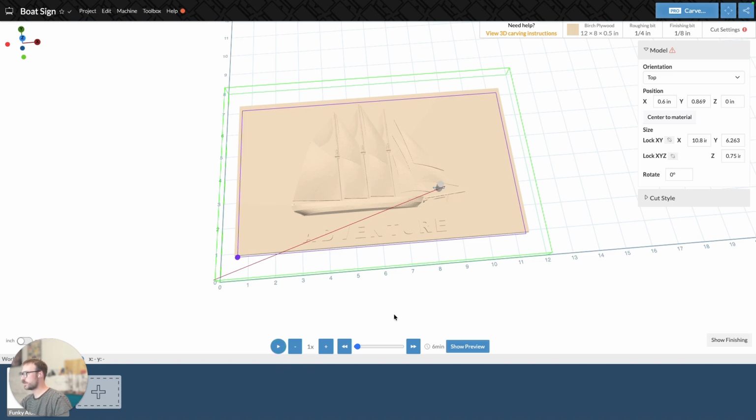That is basically where the position works out from. So if we look on the x-axis, it's about 0.6 of an inch, and that's confirmed right there, and then 0.86 of an inch up. And so essentially the position is showing from this 0 point to this purple circle what that dimension is. And so we can adjust our position knowing that information.